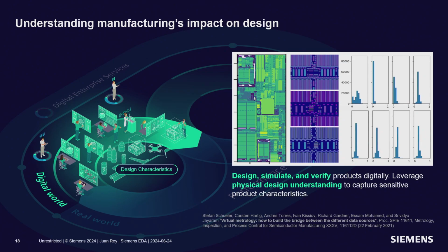So what you have is the decomposition of the layout, a small section of the layout on the top, into two layers to perform double patterning. In this particular case it was for a litho-etch type of process. What you see on the top is the overlap of the two images. So the first thing that happens is this double patterning decomposition.